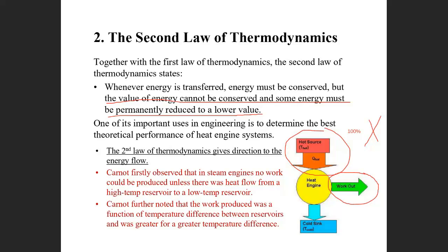There is a long history in which many scientists tried to improve efficiency and wanted the ideal, where all thermal energy is converted to work. However, Carnot first observed that in steam engines, no work could be produced unless there was heat flow from a high temperature thermal reservoir to a low temperature one. So there is heat flow in, and also heat rejection to a lower temperature reservoir, and then work can be produced. Carnot further noticed that the work produced was a function of temperature.